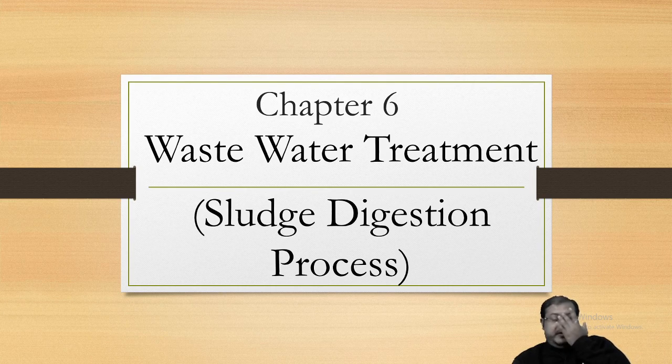Now, when you are talking about the type 4 settling process, after the settlement, what are we doing? If it is an activated sludge process, then a certain portion of the sludge will get reactivated once again. What will be the rest of the sludge? It will be thrown. Where? If it is a high rate trickling filter, once again a certain portion of sludge will get recycled, but in a standard rate or normal trickling filter, the sludge will not be recycled. Whatever is produced will go for something. It will go for what? It will go for the sludge digestion process.